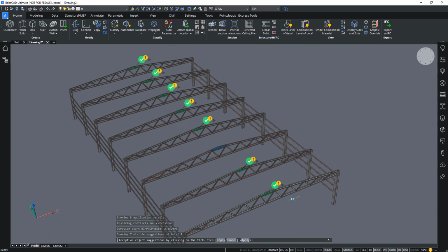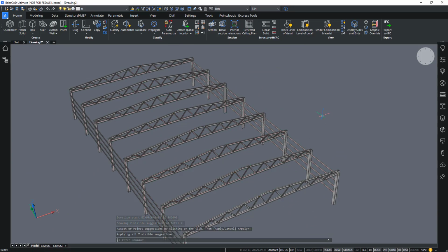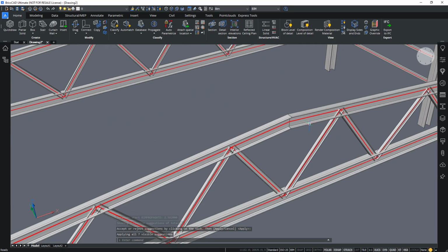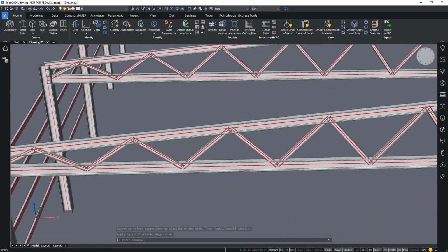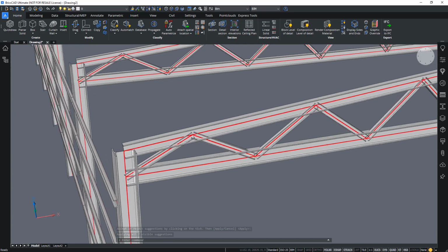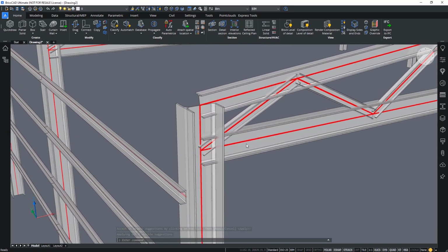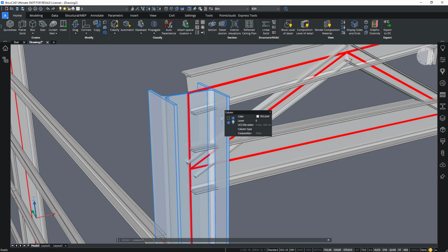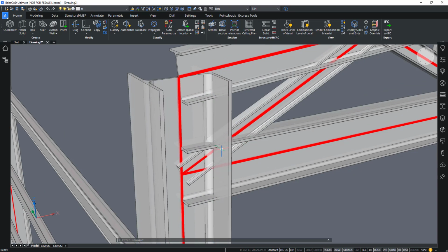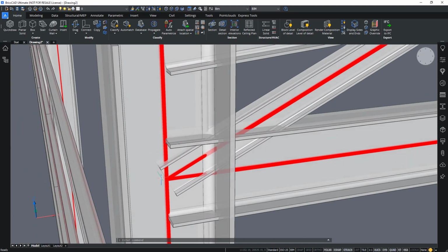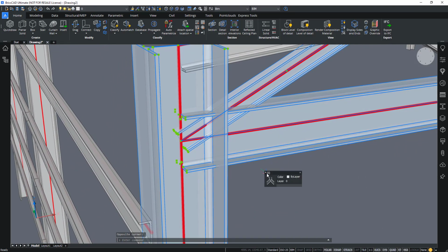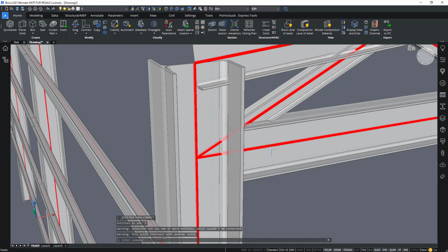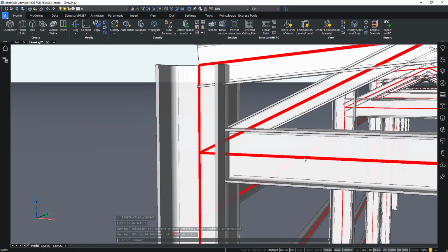And apply it to the rest of the beams like this. All right. Next up is the connection between this column and two beams here and this one member. Slightly more complicated. We'll start off with this first node here. So I'll just select the three entities and use a structural connect. And it should find a solution for me based on certain rules.